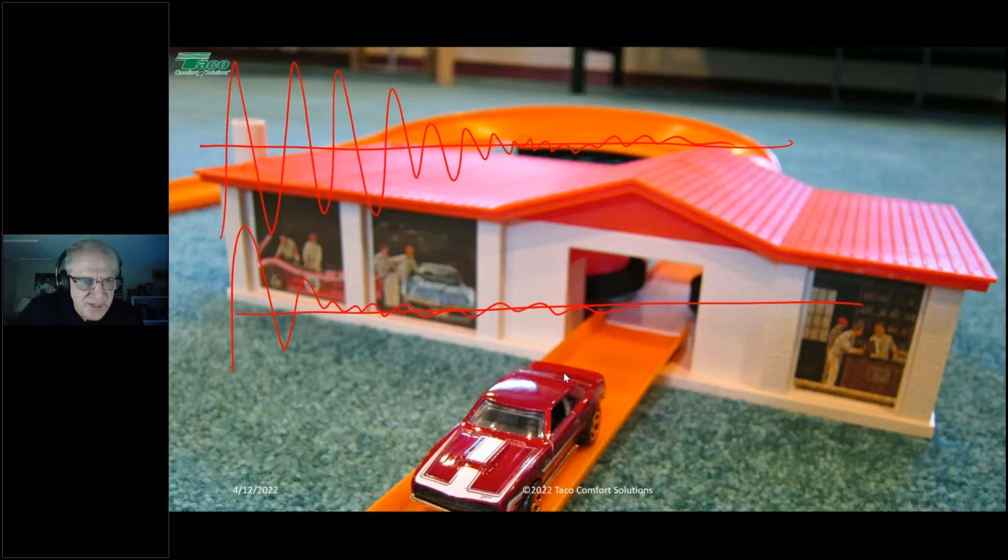I've always used line size valves for two-position and started one size less for modulating. That's a good rule to follow, Steve. Yeah, absolutely. I think that's a good rule to follow. Again, always look at the numbers too.